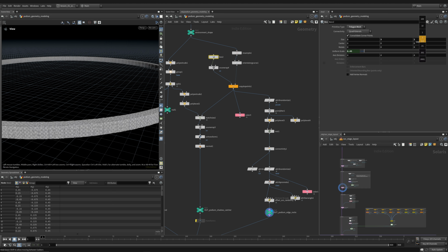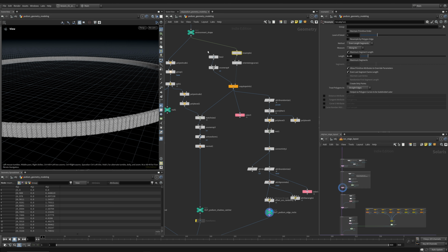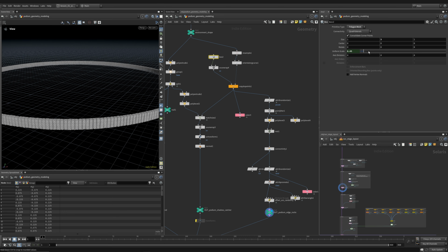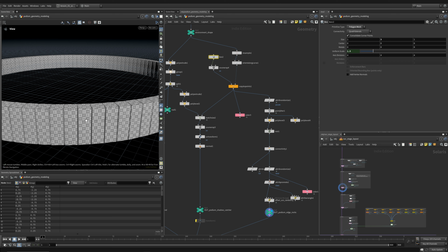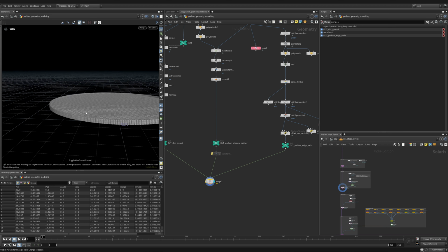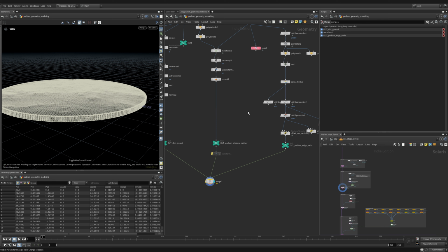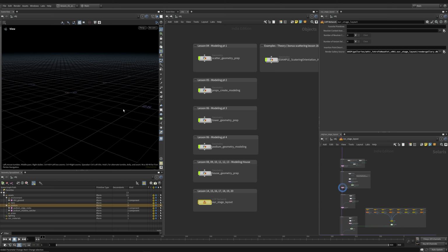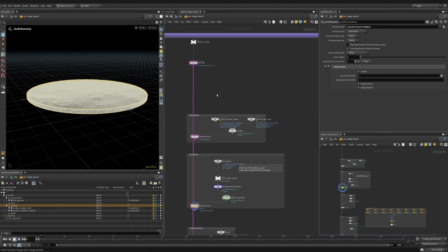And actually the reason this did intersect was because when I was referencing the size of the block for our resample here, I was referencing this scale rather than this size. So the correct way for me to have changed that would be to drag this side here, and then you'll see it can scale the box without intersecting the other geometry. So I'm going to Control Z to undo. And now we have that intersection fixed from our objects. Now U to go up, and I'm going to jump back into our stage context, which is right here, and then we'll keep going.